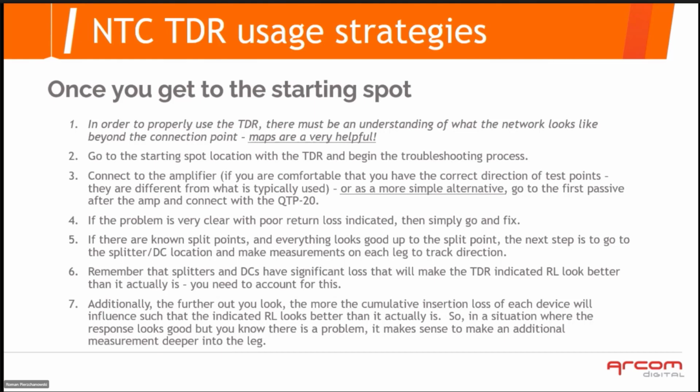And if there is indication like 5 dB return loss, then go and simply fix it. If something looks fishy around good values, but you are not sure, well, test it from a closer distance and find out if it's maybe after a splitter or a DC. Remember that when there are many devices, they add insertion loss, and everything looks as better return loss than it is. So using smart scale is a good practice whenever you see multiple peaks.